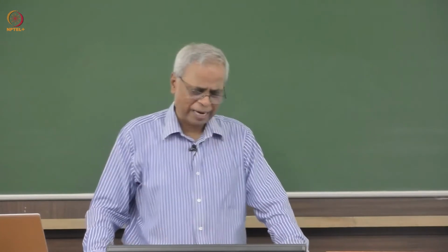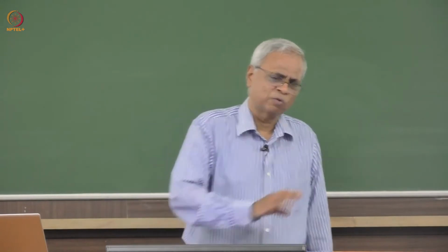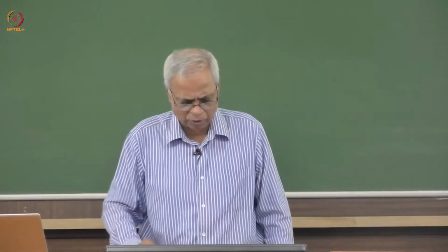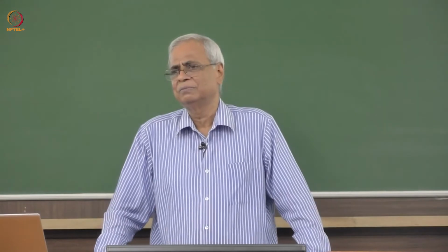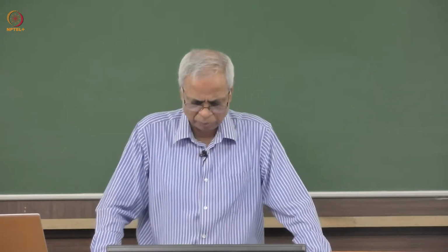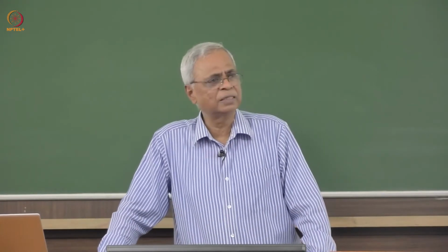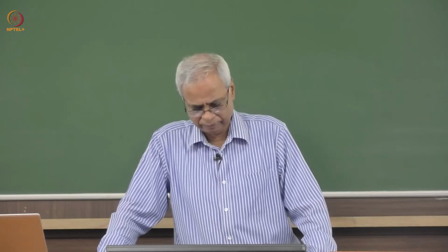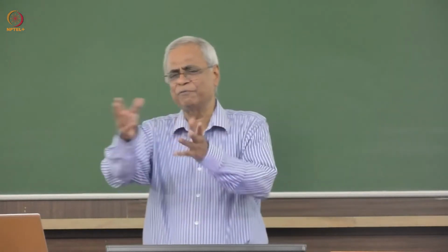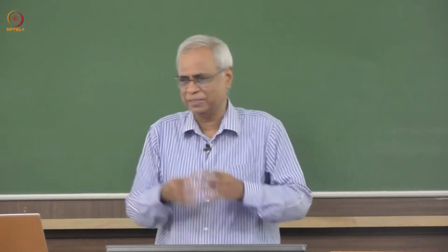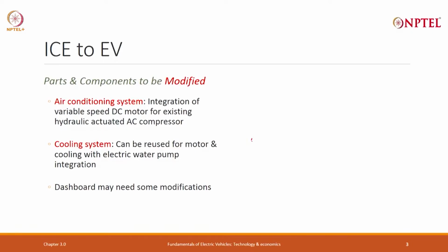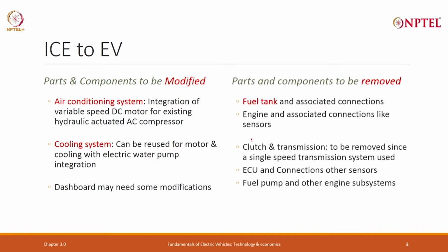Cooling systems, all kinds of cooling systems will be required, we will have to cool the batteries, we will have to cool the motors and controllers, and you will require these to be electrically driven rather than again petrol driven. Dashboard may need a few modifications, you have to add a few parameters and you can today make it more intelligent. Parts which can go away completely, fuel tank will go away completely.